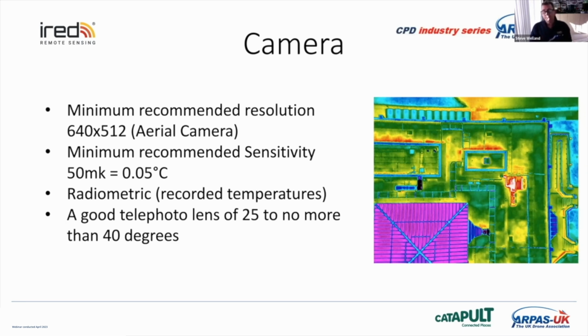It seems that manufacturers want to give us the best of both worlds. A lot of the camera drones that are out there are not designed purposely for inspection work. They're designed for the search and rescue industry, where having a narrow lens becomes less important. I wouldn't say unimportant, but less important, and probably a bit more important to have a wider field of view. The problem with having a wider field of view is it effectively halves the distance we should be or can be away from target.